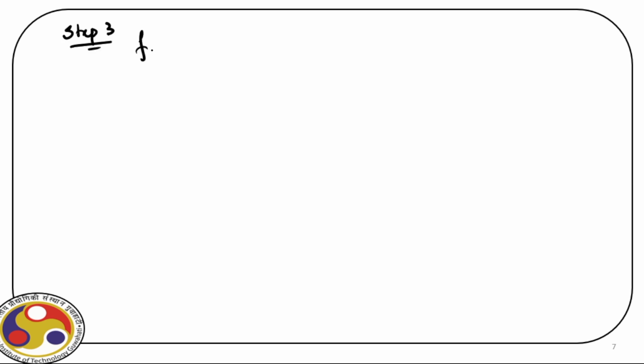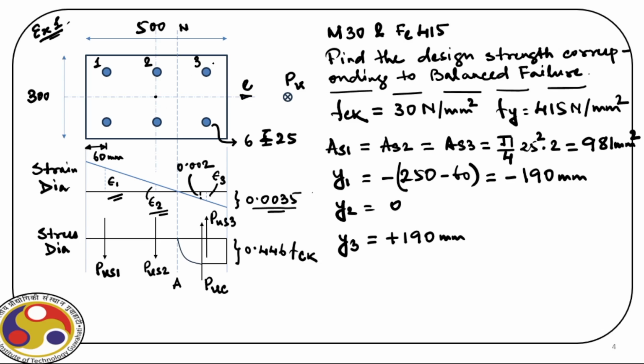Now once that is done, next step, we have to find out fC3, because for this third layer, the moment we find out its contribution, fS3, we have to figure out the stress in the steel bar and the stress in the concrete surrounding the steel bar, right? So let us do that exercise.